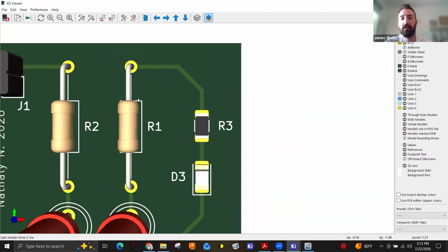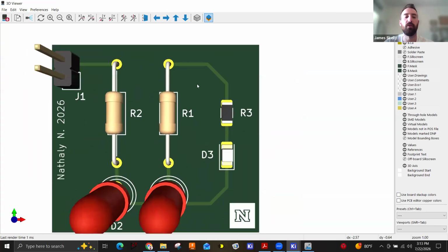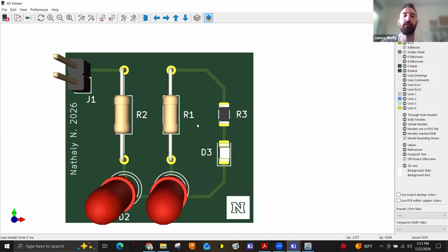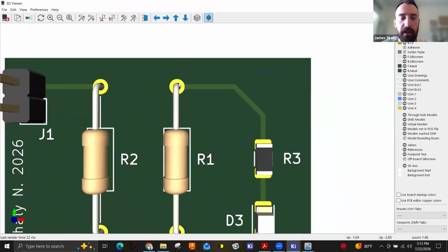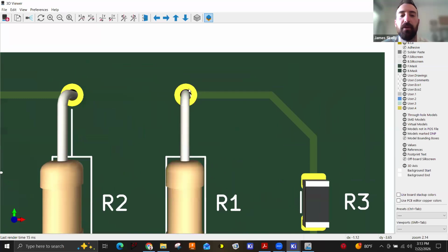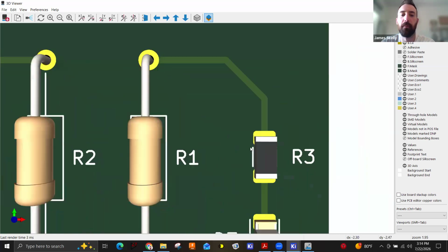Okay. So when you are ordering a PCB, a lot of the footprints and stuff that you have by default, they've already done this thing called removing the solder mask layer. Okay. So the solder mask would by default cover up all of the copper because they apply that to the whole board unless you specify, I don't want solder mask here. And all of the footprints that we looked at up to this point, they had already removed that solder mask.